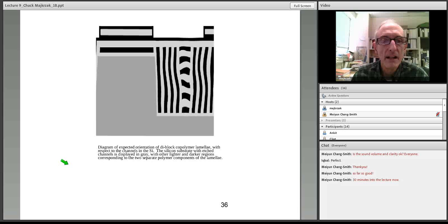And then if we take that system and we deposit it on this silicon grating structure, this grooved structure, we may find that at the tops we get a lamellae structure that is normal to the surface, whereas in the blocks we may find a different combination. There may be an ordering direction below some order-disorder transition in molecular weight that gives us stripes that are vertical here and horizontal in the middle, and so on and so forth. Just one possibility.